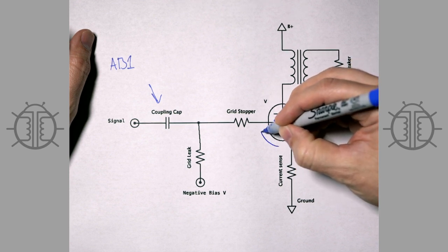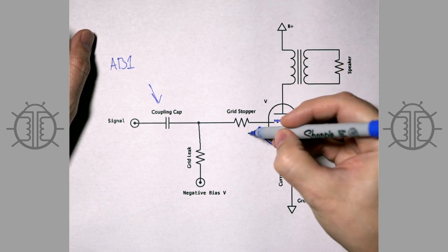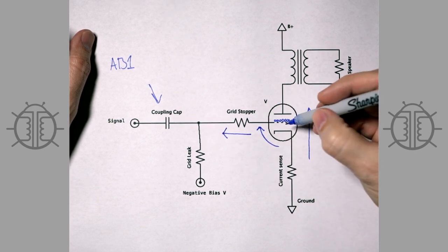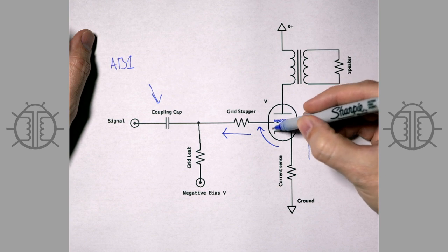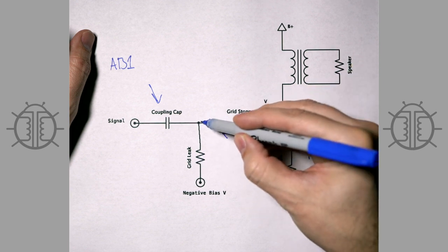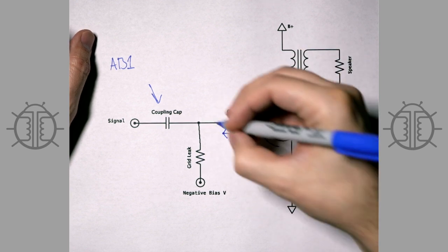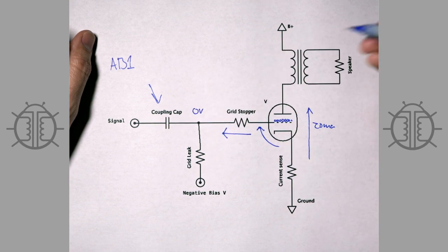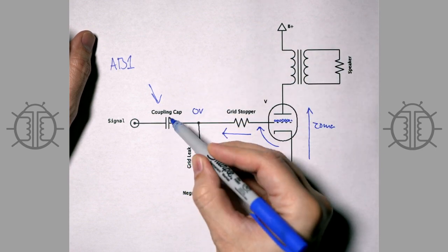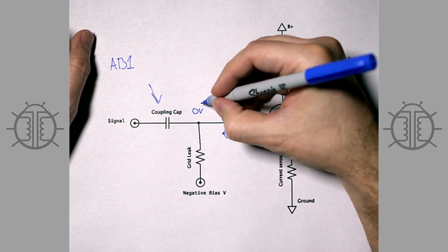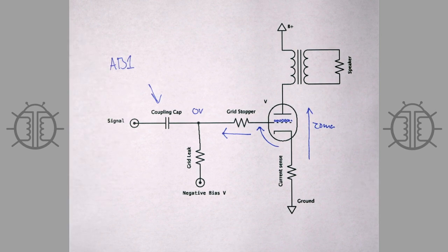So what happens with blocking is there are some situations where electrons can flow from the cathode this way. And why that happens is there's something like a diode action here between the cathode and the grid. The reason is if this area over here becomes, let's say, 0 volts, or even positive, like if this cap fails here and some of the positive voltage from the plate of your previous stage gets over here, this could even become positive.